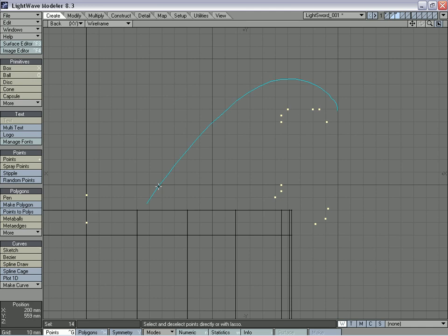Okay, we can delete that point, actually deselect all these points first, and delete that point. Copy and paste to move it up, and that way we have a straight line. And edit that rounding, and then delete these points and just mirror that over, and we can delete that point, copy it and paste that down. Undo, make sure we constrain that when we pull it, and this is a very tight curve in here.